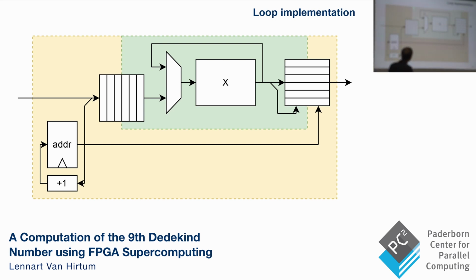It also has a very nice benefit, which is this green dashed line here, but I'll get back to that in a minute. But the one big drawback this module has is, what if we're too late? What if this module computes a certain element too late? Let's say an element takes 30 cycles to compute, or maybe 2,000 clock cycles to compute, and you only have 1,000 addresses here, then you'll have visited address 1,000 or whatever address it was given before it actually got written. And so then our hardware performs faulty.